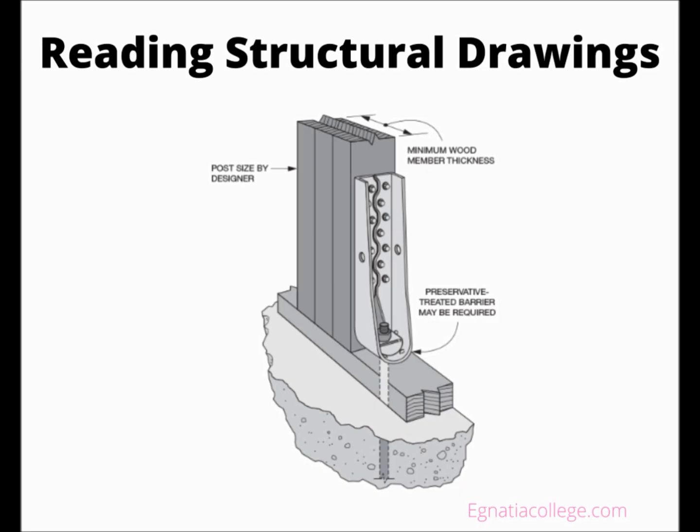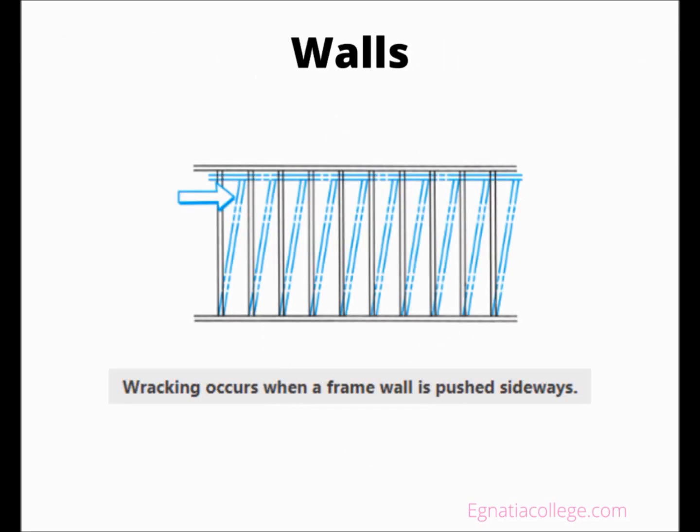Usually they bolt to a post or studs in the wall, but can also be nailed to the post or studs. They are a critical part of the shear wall design. The other anchoring system is a series of foundation anchor bolts embedded in the concrete that bolt the wall bottom plate to the concrete. This resists both uplift and lateral displacement.